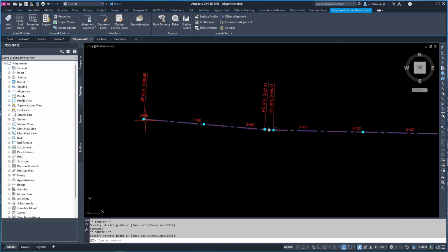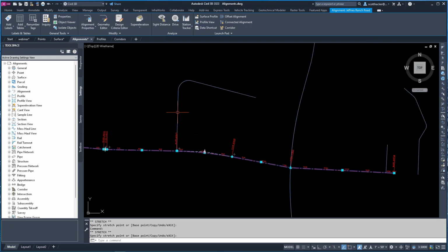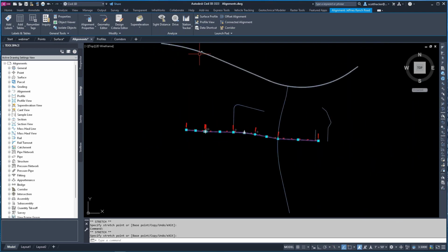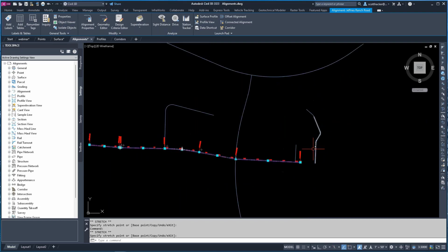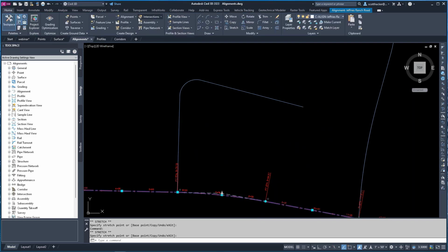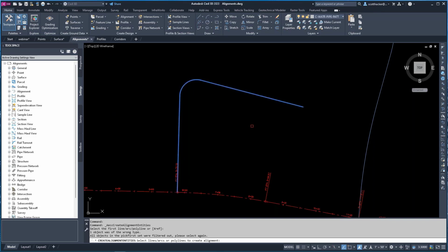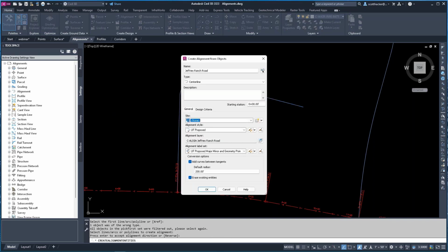Civil 3D labels. So we would go ahead and create our other alignments here. I've got Mission Avenue, Rand Boulevard. I've got a couple of odd ones out here. We've got Ascent Place. The process is the same. Once you get that process down, you're going to be able to do any kind of alignment that you want.